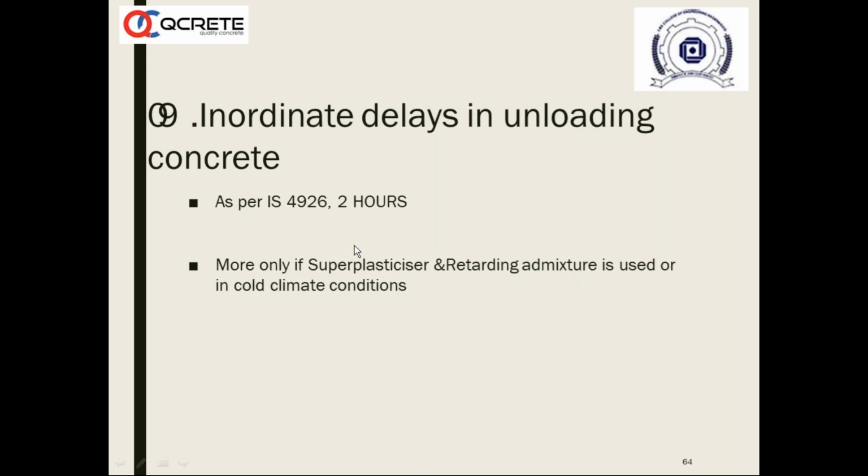You cannot have delayed concrete used in the structure. There are people who use it after 5 hours, 6 hours and so on. Definitely the concrete will not give that much strength. It will not have the properties as designed and desired. We need to be very careful that we should not use concrete more than 2.5 hours after cement is mixed with water. That is, once the water comes into touch with cement, from that point you need to take 2 hours to a maximum of 3 hours, especially for high strength concrete. You need to pour the concrete as early as possible.